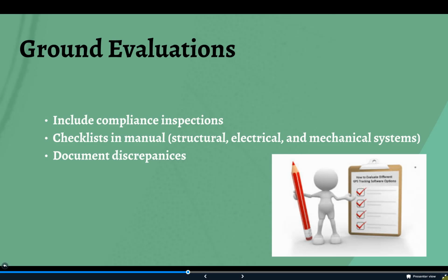Aircraft ground evaluations include compliance inspections, but in a broader sense. The participating engineering unit member will be looking at the modification with respect to other installations that are on the aircraft. The hope of the FAA is that an EUM's eyes will be able to see modification interface issues that can't be seen in a drawing or substantiation report review. Since so many airplanes are unique because of the various changes an owner may have made, this is another check to make sure certain assumptions made are valid.